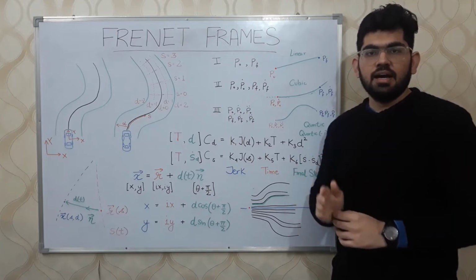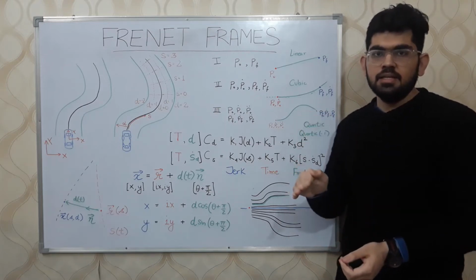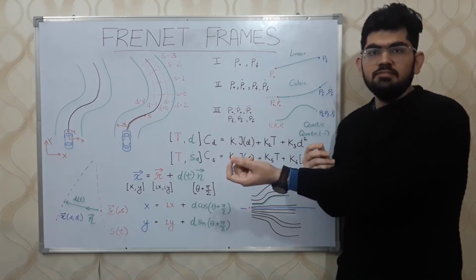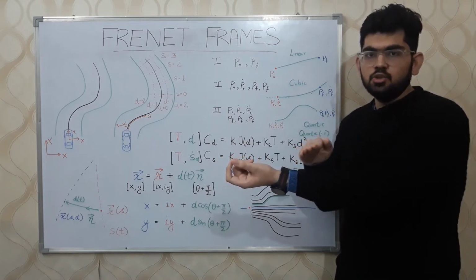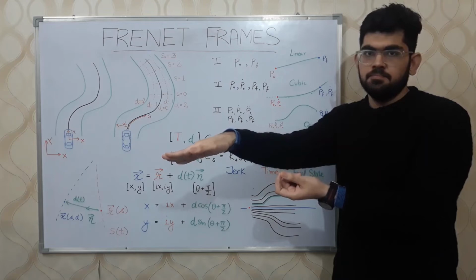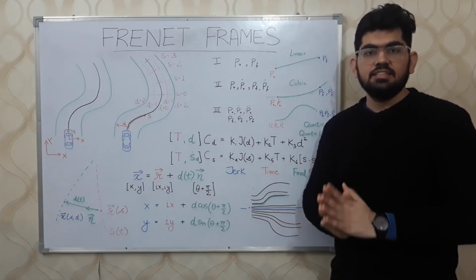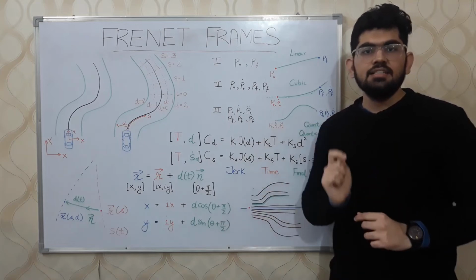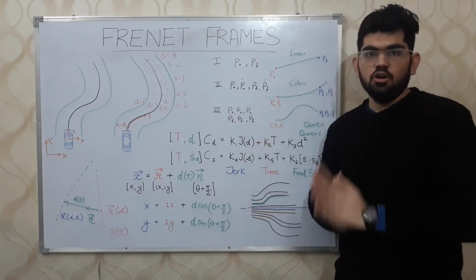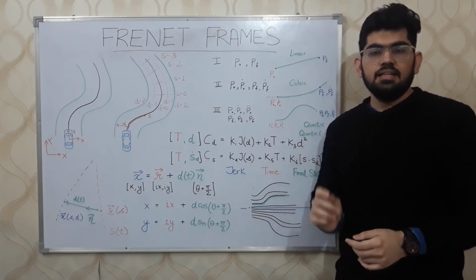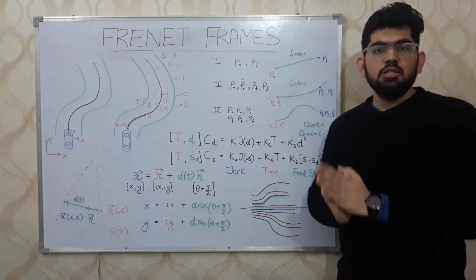For this scenario, we want our car to only go and maintain a particular speed. If we want our car to maintain a particular speed, whenever an obstacle comes in front of the car, the only way the car can maintain its speed is to overtake that obstacle. Since we want a constant velocity, the acceleration along the s direction needs to be 0. Also, due to the constant velocity, the final s can take on any value since we do not have a final destination in mind.